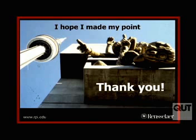Okay. Yes? You mentioned you're looking at using pulse wind streams to use resonance in your favour. Have you got an idea of what type of magnitude reduction you might achieve from that? Well, you saw about a 5%, maybe 10%, if we're lucky, reduction in the amplitude, but it was the frequency change that was more important because that changes the wind speed dramatically, and so that changes the return period that I have to worry about.